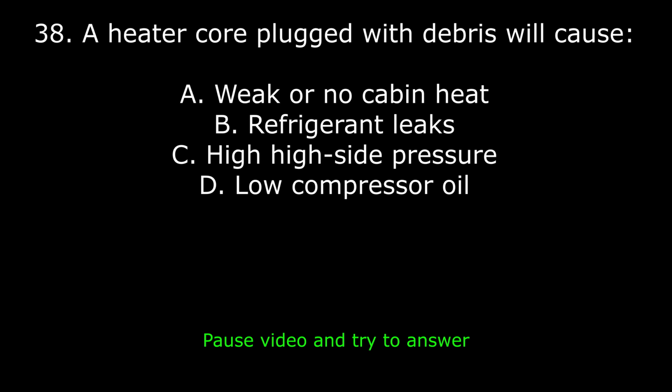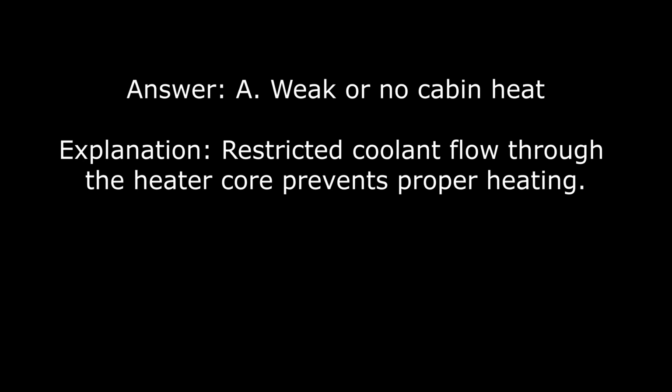38. A heater core plugged with debris will cause: A. Weak or no cabin heat. B. Refrigerant leaks. C. High side pressure. D. Low compressor oil. Answer: A, weak or no cabin heat. Explanation: restricted coolant flow through the heater core prevents proper heating.